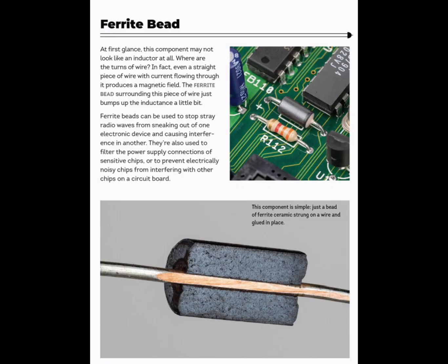Ensure the bead can handle the required current without overheating or saturating. Check the impedance profile over the relevant frequency range to ensure effective noise suppression.